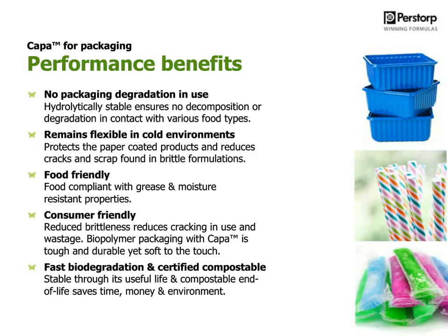Well, looking at the stability of the product, it's hydrolytically stable. So when it's used in packaging and comes into contact with different types of foods with various pH, it will not degrade and it will remain stable. And in some cases, it can also stabilize the packaging as such. Thanks to the low glass transition temperature, it will remain flexible in cold environments.